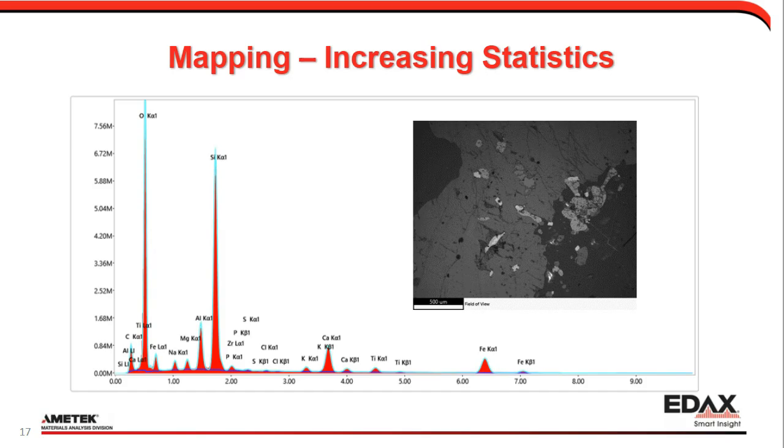There are some iron inclusions and calcium inclusions, aluminum. There's some salt in there, sodium and chlorine, probably mostly from dirty fingers, as we've been using this sample for a while. And we also have a phosphorus and zirconium overlap, which makes this one pretty interesting. That is the small peak you see just on the right-hand side of the silicon peak.